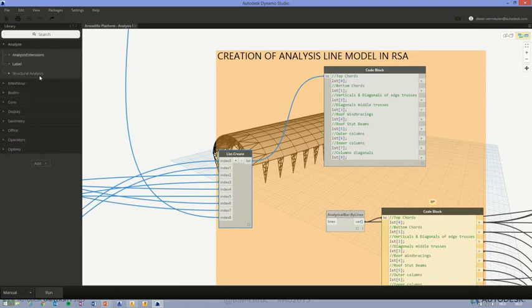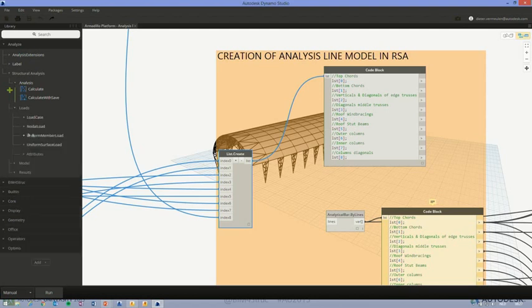So if something changes now in Dynamo, if I change the truss height, then it will change here again. It will regenerate. It won't create a new structure. It will regenerate the structure and reposition the objects in the right order. But the element IDs remain consistent. Question: if you're hosting or putting embedded information in structural elements, and you tweak it in Dynamo and update the geometry, or any other embedded data that was added after the fact, is it all retained or does it recreate the structural number?